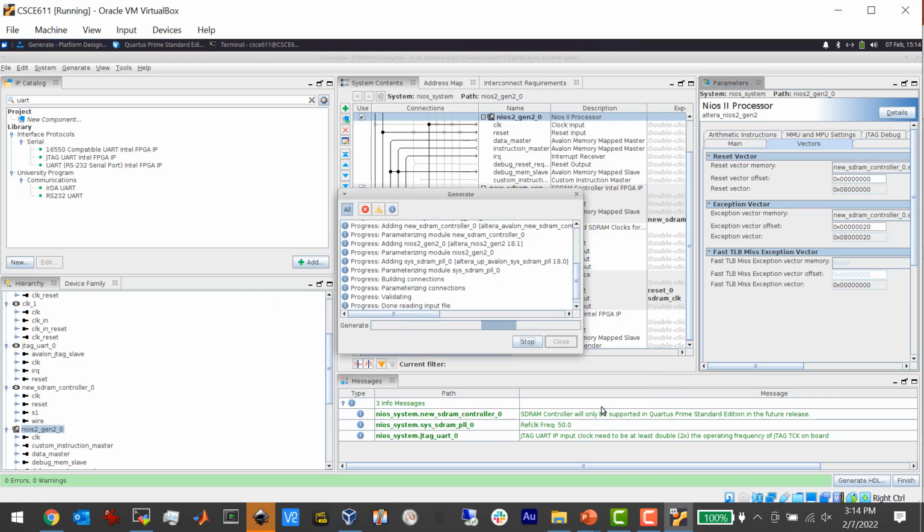Now it's going to run a bunch of Java/Perl hybrid monstrosity Frankenstein stuff to generate this. What it's doing is generating the SystemVerilog code needed to essentially assemble this whole thing in hardware, right? So you could design this by hand, but it would take forever. Basically, what this is doing is automating the process of designing a very complex system.